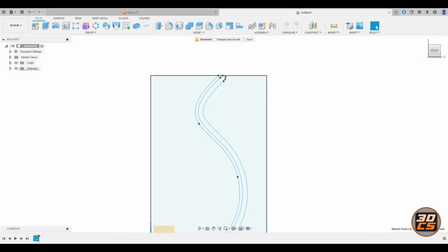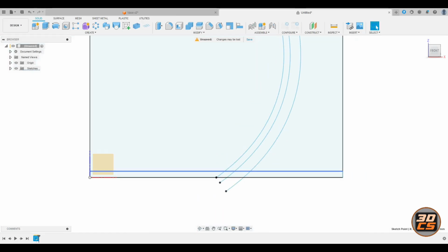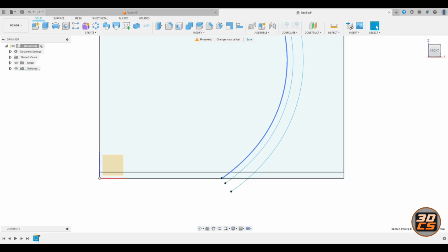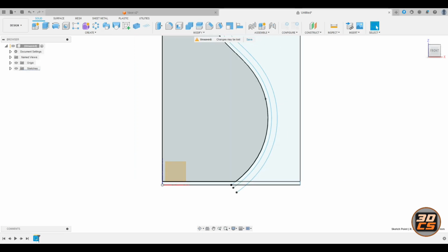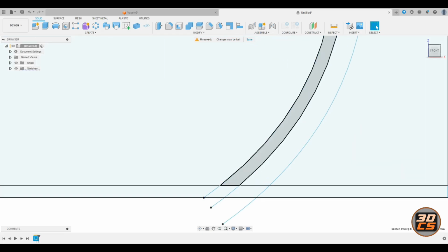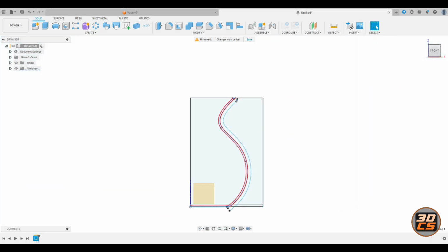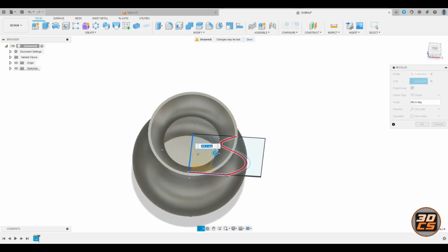Finish sketch, and that's it. So now in the videos on YouTube, you used to see the guys revolving all these portions. So I will do differently. I will select this, and then I will revolve only this portion. In this way, we have the vase already empty inside. This will help a lot because sometimes when you create a shell, you have a problem on the creation.